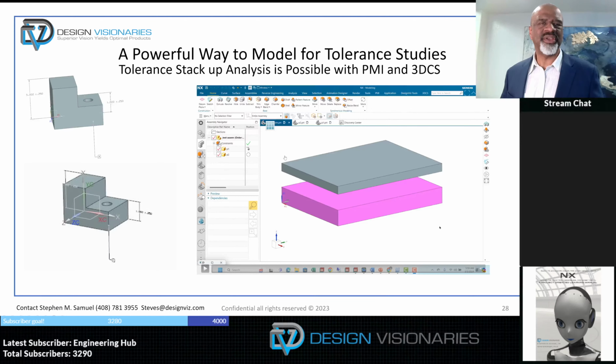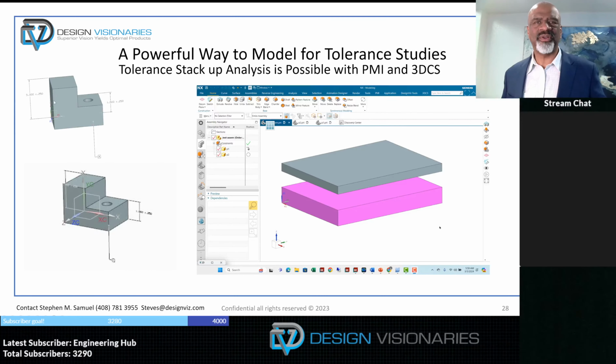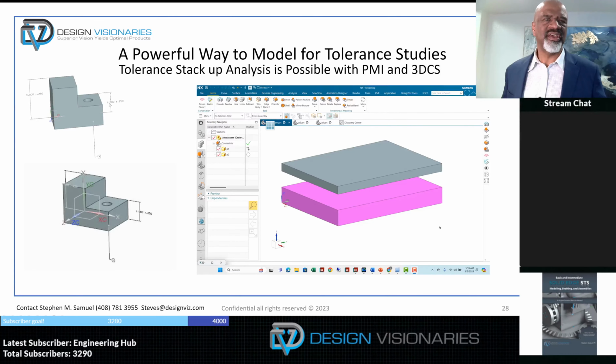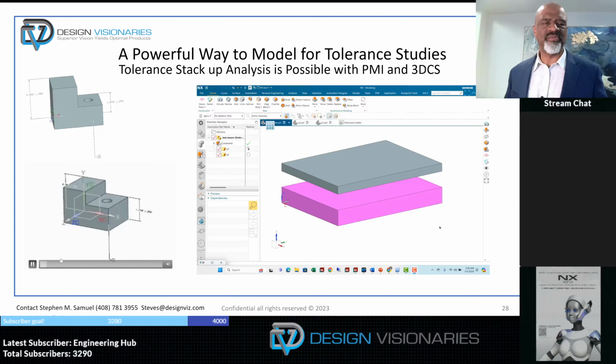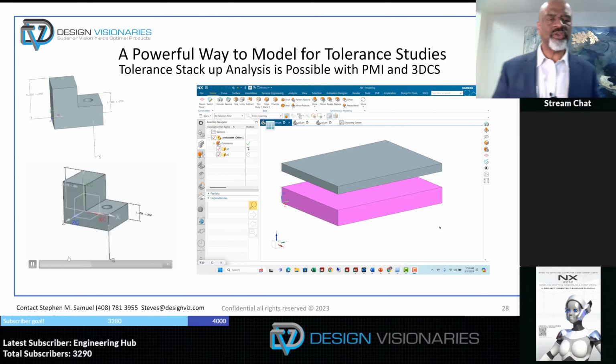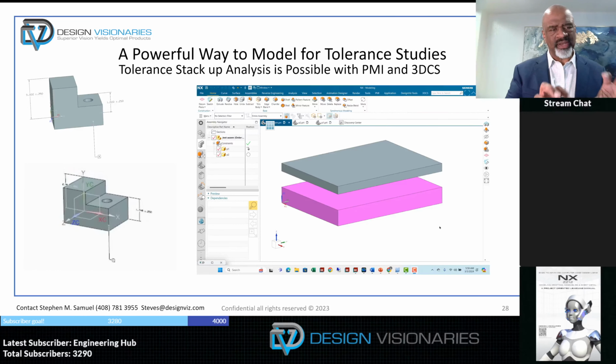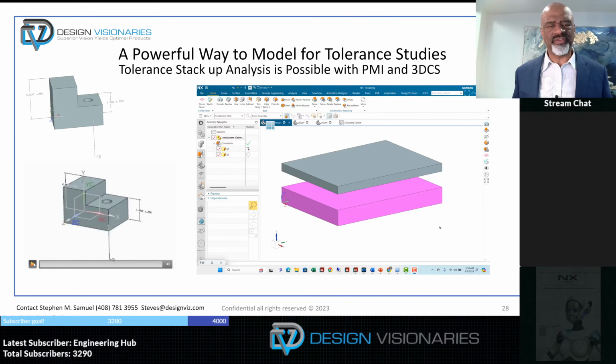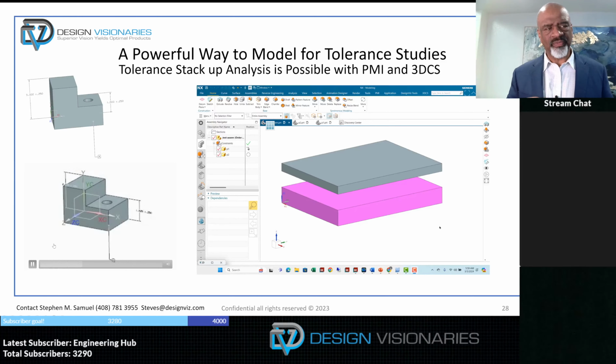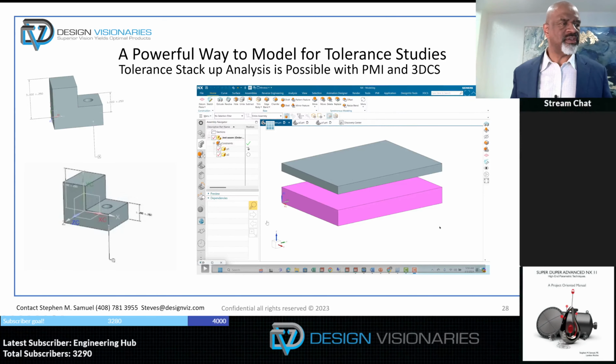So here we go. Just imagine that this little component on the left-hand side has a 1.5 inch height with a 0.25 plus or minus tolerance. Now that's a huge tolerance, but I did that because I just wanted to show you that the modeler can now take your model and, I'll say, perturbate it, really show you the result of what happens when you have different tolerance schemes in real time, just like that. And the beauty of this is you can very easily use the plugins.